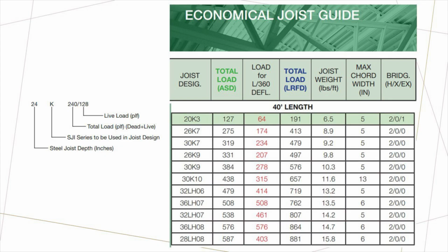The engineer of record provides the joist manufacturer with the required live load, total load, uplift, any snowdrift conditions, and the appropriate joist type, whether it's K, KCS, TCX, LH, or DLH. The joist depth required varies with span, and tools like Vulcraft's Economic Joist Design Guide make it easy to identify cost effective options. These joists then frame into the beams, which must be designed for the governing load case.